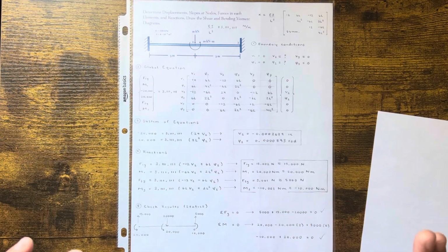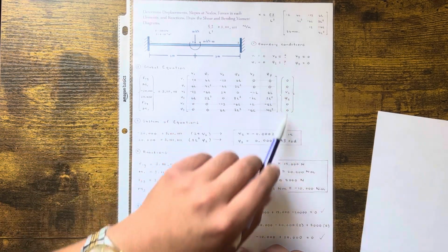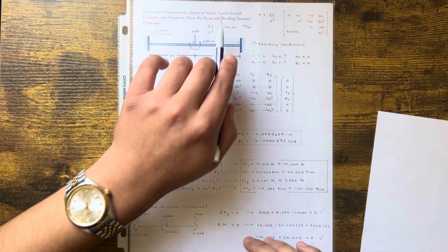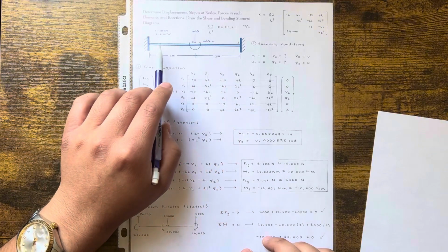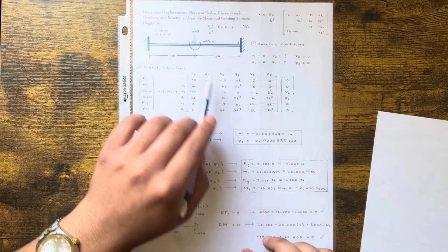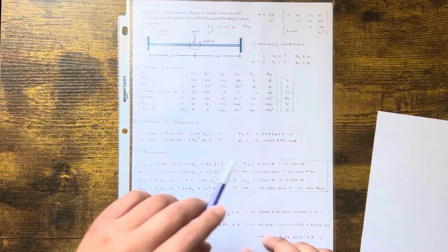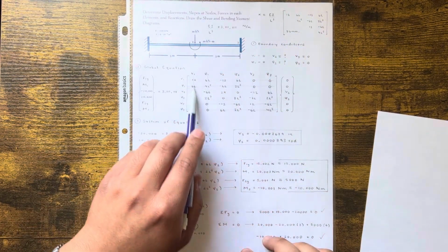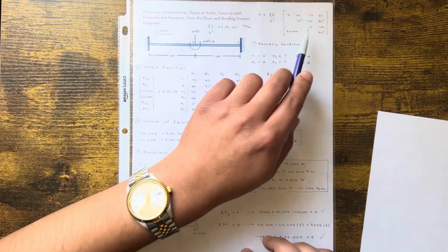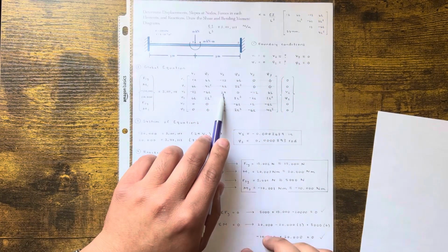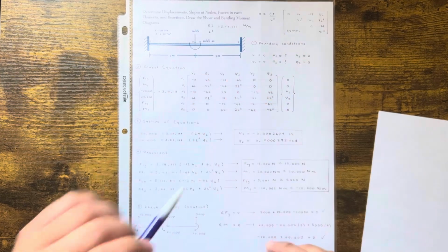So now that that's correct, we verified all the force vector and the displacement vector. So now we're gonna find the forces in each element. Easy, right? We got 2 elements. This one's between nodes 1 and 2, and this one's between nodes 2 and 3. And we're gonna use this K matrix, not this one. You're not gonna use these 16 values for element number 1. You're going to use this one right here, 12, 4L squared. I don't want you to use 24, 8L squared, 0 and 0. You have to use just the beam stiffness, okay?